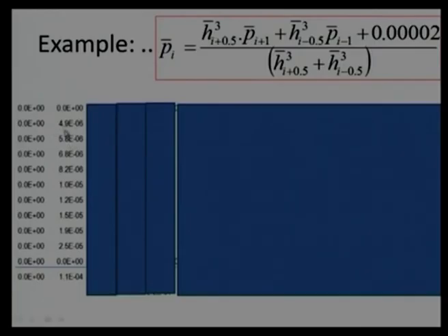So, sequentially we go ahead and get the values, and we are able to see the pressure value is continuously increasing. There is already one source term plus an increase in the pressure term. Compared to 0, it will be a higher value. So, that is why the pressure value is increasing, up to a maximum at node number 10. Of course, node number 11 is a boundary value, and we have already specified that the pressure value will be 0 there. That will not change with any iteration, it will remain the same.